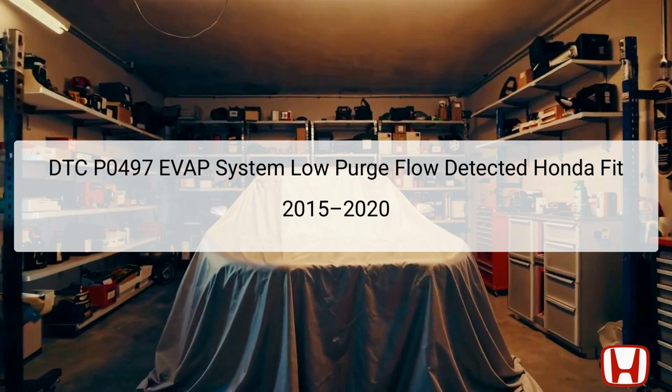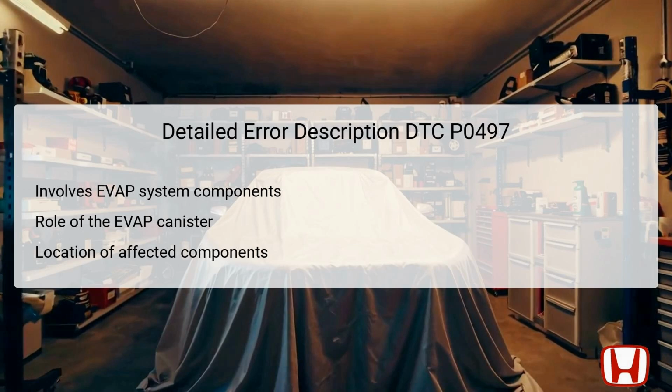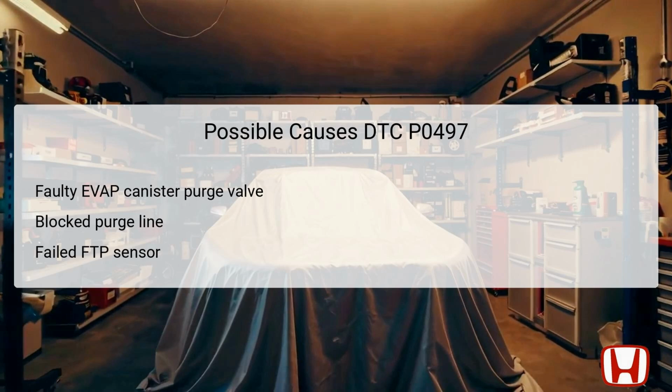A malfunction in these areas can adversely affect emissions control and may lead to suboptimal engine performance and increased hydrocarbon emissions. Error code P0497 specifically affects elements of the evaporative emission control system. The causes of DTC P0497 can include a faulty EVAP canister purge valve, which may not be functioning correctly to allow vapors to flow as needed. Additionally, a blockage in the purge line between the valve and the canister can hinder vapor movement, leading to low purge flow detection.